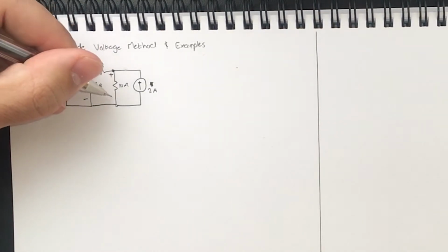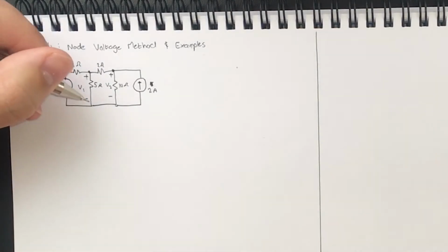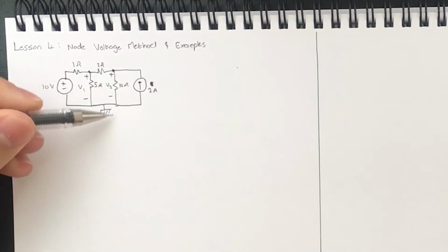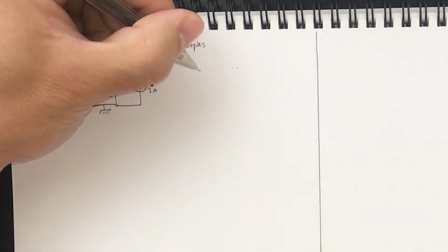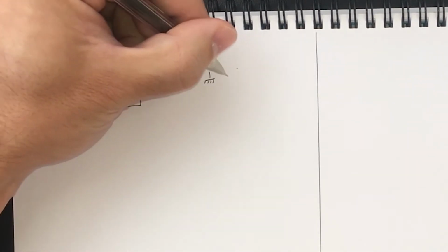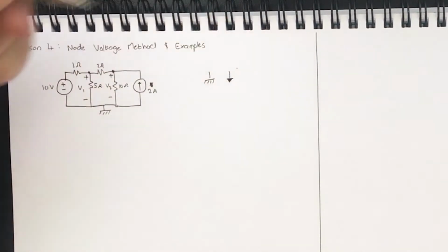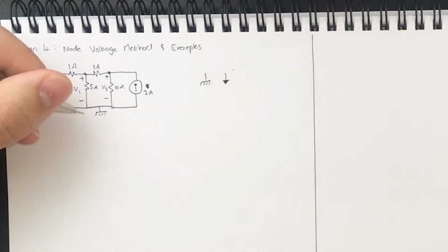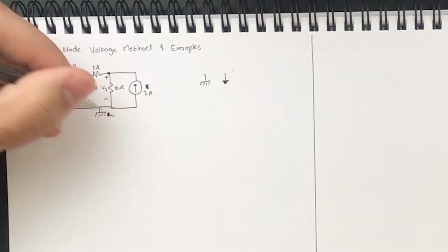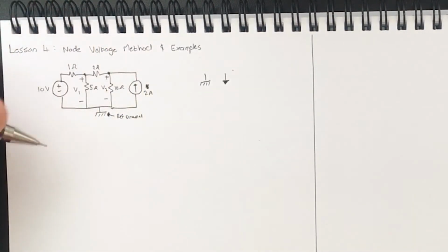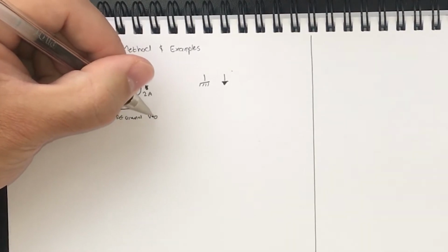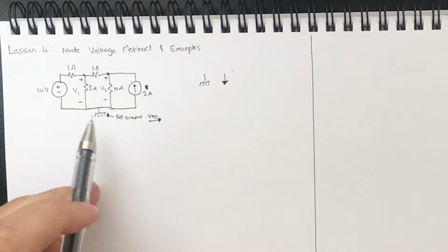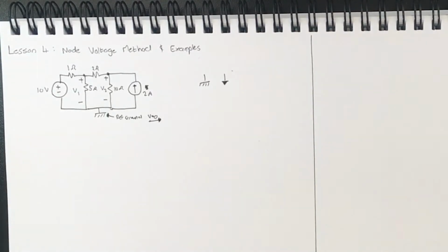and another voltage, V2. Very importantly, and a trick that we often use within circuit analysis, is to define a reference ground. A reference ground can be symbolized through this symbol or this symbol. I always prefer this symbol. A reference ground allows us to define an arbitrary point where V is equal to 0. And this really simplifies our equations.